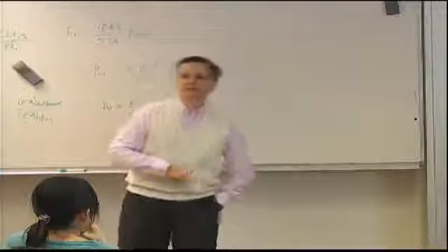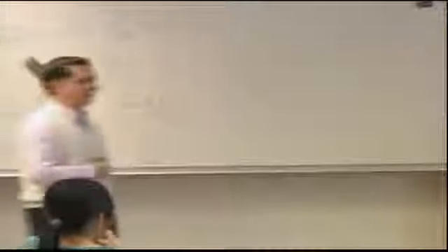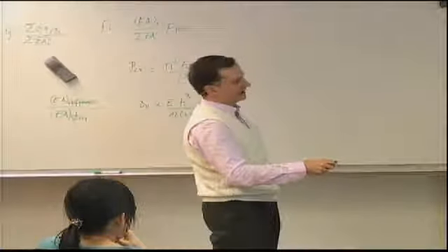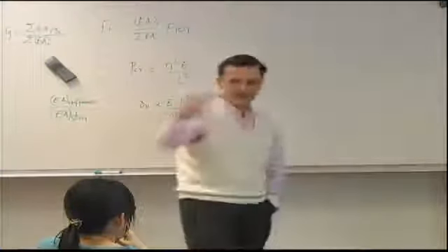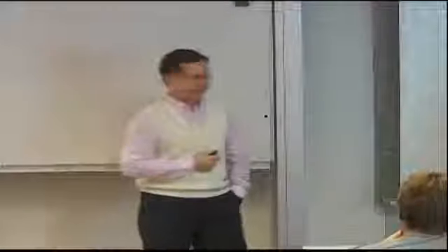So basically here, inter-rivet buckling is not a driver, and you can use any spacing as long as it's more than 20 millimeters, and you would be fine both from the perspective of avoiding stress concentration enhancement and from the point of avoiding inter-rivet buckling.